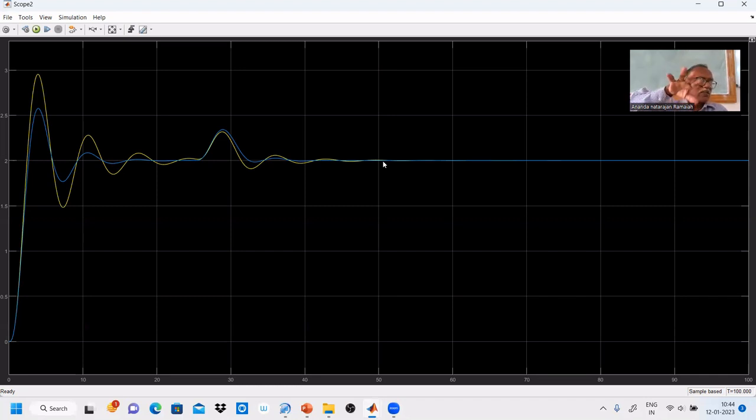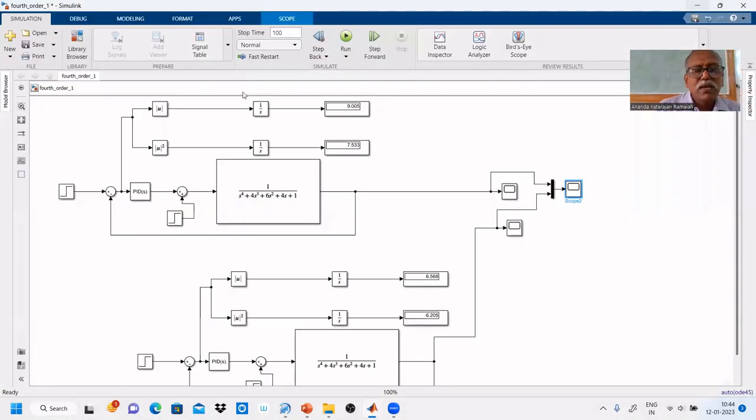The regulatory response will bring the process to the set point. What is the set point now? 2. That's why the process variable is brought to 2. So, combining both together, you see which gives better ISE and IAE. In both cases, if we combine these together, the continuous cycling method gives a better response. We trace this and we will get it.